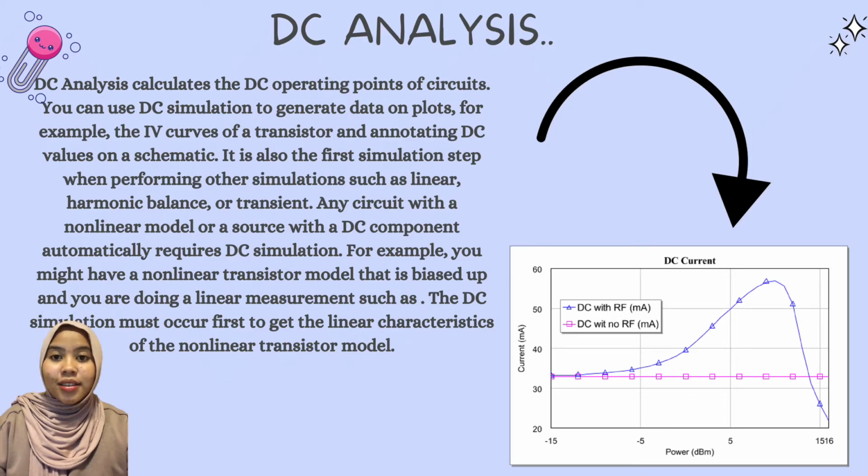DC analysis. DC analysis calculates the DC operating point of the circuit. You can use DC simulation to generate data on plots, for example, the IV curve of a transistor and any DC value on a schematic. It is also the first simulation step when performing other simulations such as linear harmonic balance of a transistor.